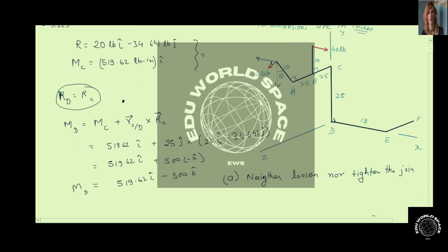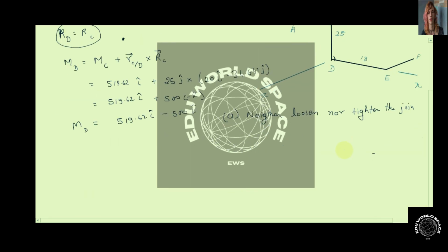All right. Now in the second part, they are asking what the effect will be for the pipe DE. Since the moment about point D we have already calculated, if we see the actual diagram here, the elbow at point E will have an opening along the x-axis, so the pipe DE can only be rotated if it has a moment along the x-axis.